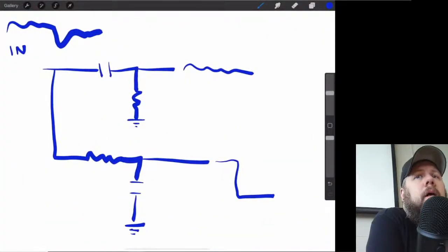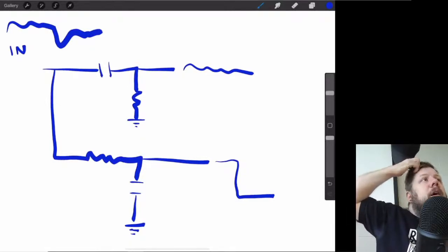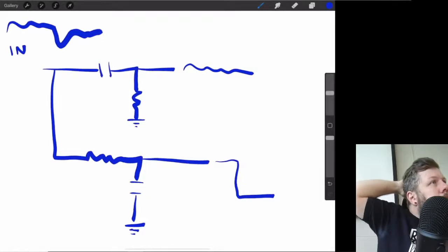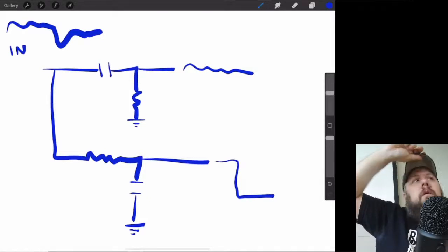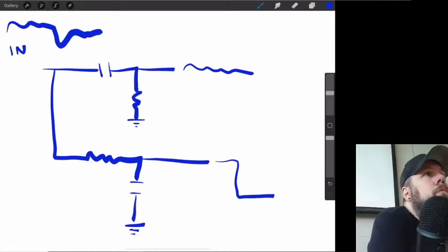When we've got delicate electronics that use voltage to carry information back and forth, if our power supply is all wrecked and has a whole bunch of noise from just, like, the hair dryer that your wife is using or something, then it's going to get a lot of spurious data. Well, we can filter that stuff out. We can filter that high frequency stuff out if we need to. Okay. So this is what we're going to do. All right.